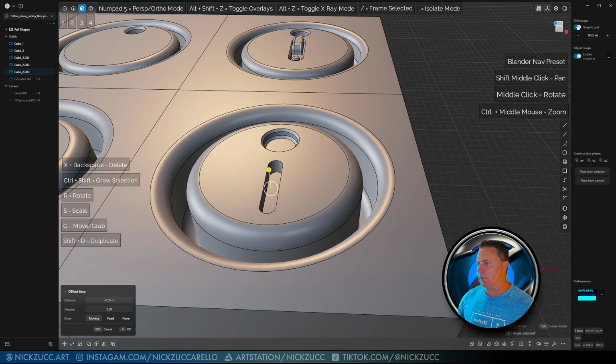So I'll just hit the period key now to bring this whole thing back. And what I can do now is tap 2 with this. I don't like that when I changed those control points, it really changed the shape of that quite a bit. So I'm going to go back with the period key and just leave it like that. But what I could show you right now is if we've got our curve selected, we could type P for the pipe command.